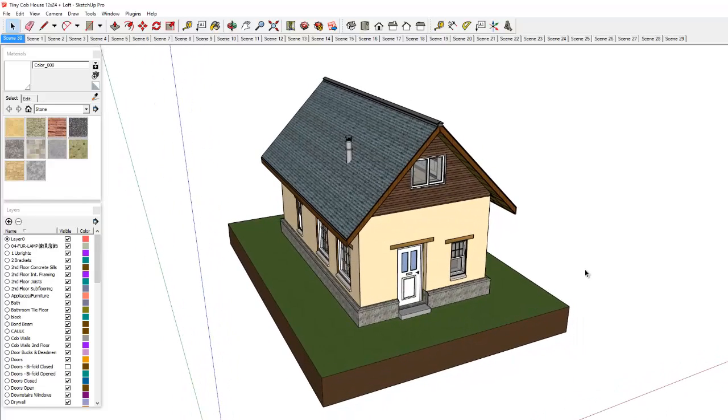You want to kind of think about when you want to have a completed building, and when you can actually get the building done. So earth materials are difficult to work with in the cold weather, especially Cob, because you're working with your hands with wet material, which is not fun in the cold. Things like rammed earth are easier to do in the cold weather because you're not so hands-on. But a lot of your foundation work can be done any time of year.